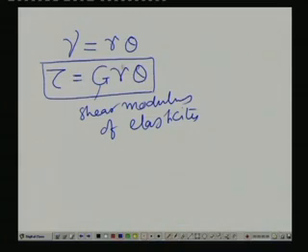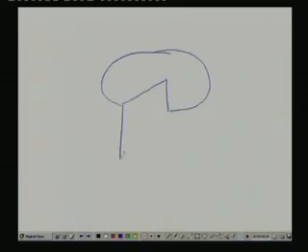Now, that means what we can see is that if theta is constant, the shear stress variation is linear. In other words, in a figure, if we consider the piece of cake sort of idea, then the shear stress variation comes like this. Okay. This is a linear variation.